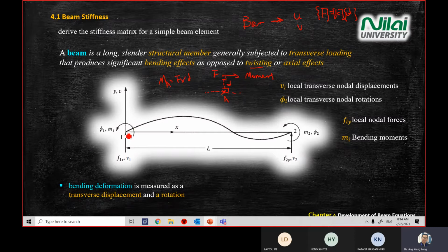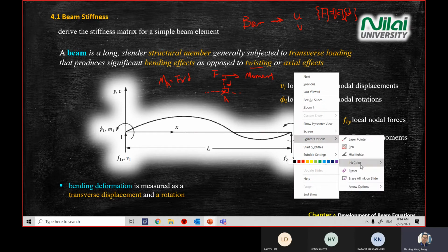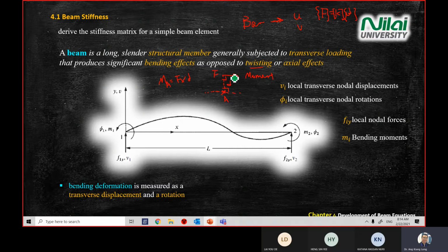So why do we not focus on x displacement? It is because if you move your force to this line, the D will become 0. So if you take the force times D, you'll get 0 moment at point A. Same with this case. Just take note that for chapter 4, if you talk about beam, we don't have horizontal or x direction moment or torque. So again, for beam, we only look at displacement in y direction.